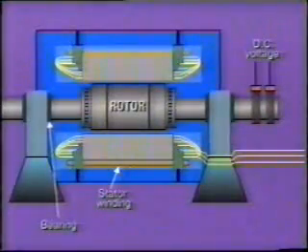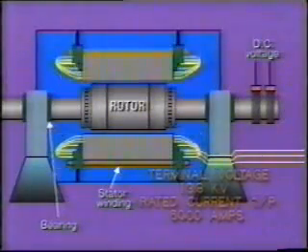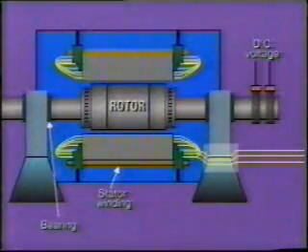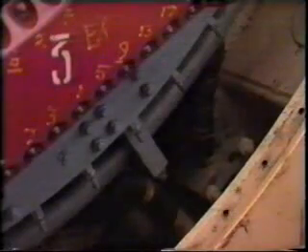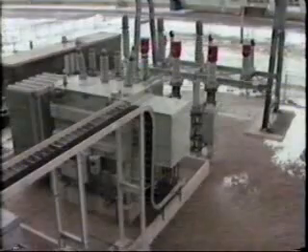The stator conductors are connected together in various series and parallel arrangements so as to produce the rated terminal voltage, say 13.8 kilovolts, and rated current output, say 6,000 amps. The stator windings are connected to the terminals, usually at the bottom of the generator. Outgoing conductors will be connected at these terminals in order to carry power to a bus or power transformer, and perhaps an auxiliary transformer.